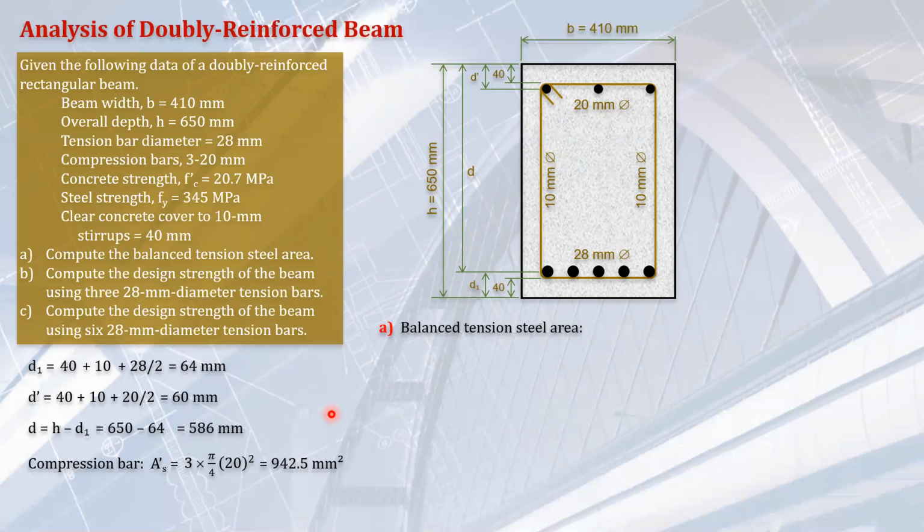That's the steel area where the tension steel just reaches the stress of Fy, in this case 345 MPa. That's all. The tension steel stress is exactly equal to Fy, 345. Now, we have the formula for the tension steel stress from the extreme fiber: 600 times (d minus c) over c. We equate that to Fy.